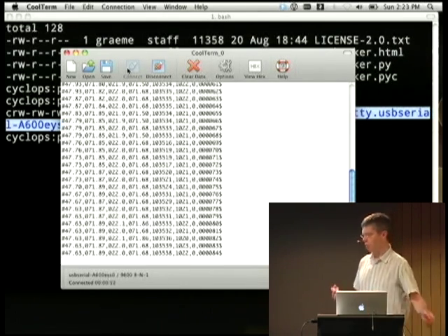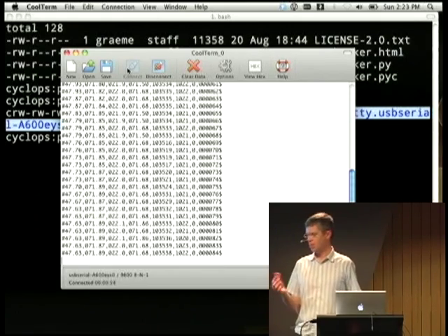If you were going to write your own weather station for home, for example, you could just get one of these boards, drop it in something like just a small plastic box that is optically clear so you still get your ambient light, stick it outside, USB cable inside, maybe 10 lines of Python, if that, and you've got a fully working weather station. That's not bad.